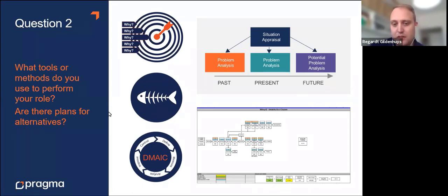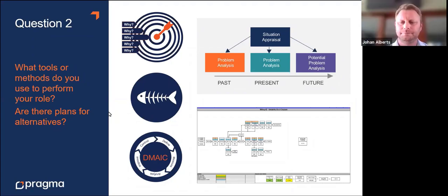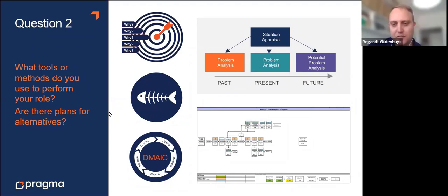It's a tool that unfortunately the asset maturity must be at a certain level for you to use it reliably. It's dangerous in the sense that if I tick all the boxes, if I fill in all the information that the software requires, it will give me an answer at the end of the day. But how useful is that answer? So very powerful tool. You'll of course need to do FMEAs previously to determine what your top failure modes are, your critical assets, as well as a good history of your delay analysis in terms of your MTBFs and your MTTRs. But as you said, there's two ways to approach it.